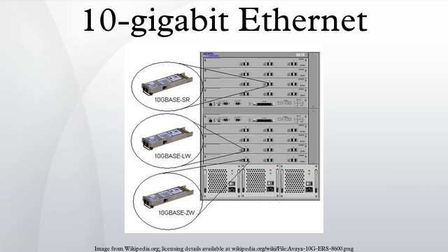10GBASE-T cable infrastructure can also be used for 1000BASE-T, allowing a gradual upgrade from 1000BASE-T using auto-negotiation to select which speed to use. 10GBASE-T has latency in the range 2 to 4 microseconds compared to 1 to 12 microseconds on 1000BASE-T. As of 2010, 10GBASE-T silicon is available from several manufacturers with claimed power dissipation of 3 to 4 W at structure widths of 40 nm, and with 28 nm in development, power will continue to decline.